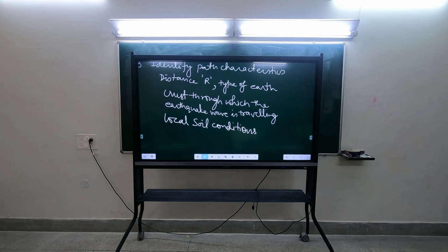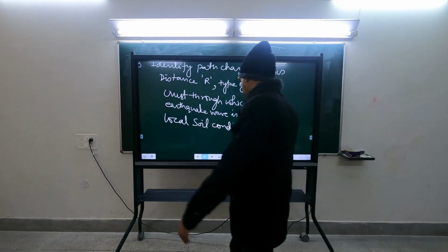Moreover, in soil the attenuation will be very fast. In rock, it can travel long distances before dissipating all the energy. In soil, it will dissipate energy very fast, because the damping in soil is much more than in rock. So any energy you input in rock can travel very long distances, while in soil it will travel much shorter distances. So you need to consider that.